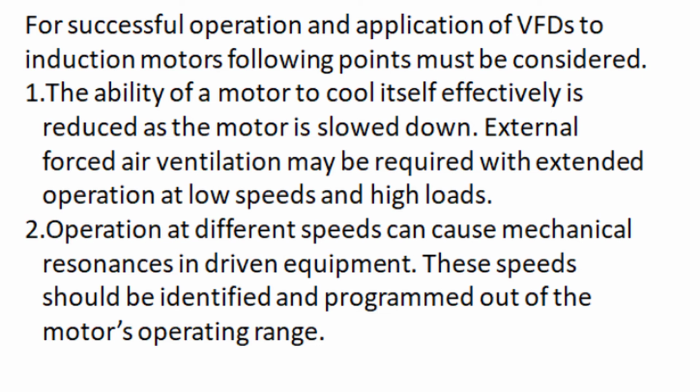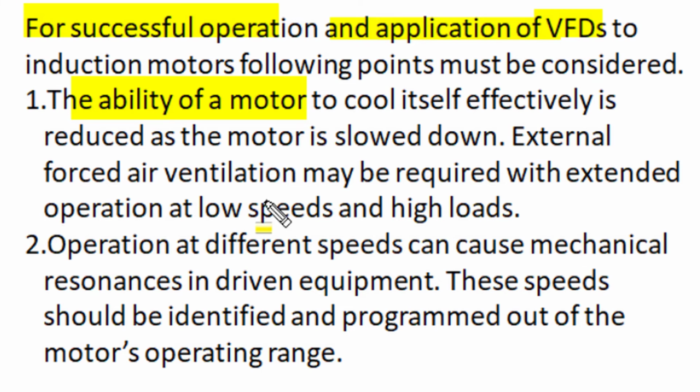For successful operation of a variable frequency drive in the application of variable speed of induction motors, the following technical points must be considered, and they are very important. The key points are: the ability of the motor to cool itself effectively also gets reduced. So in such slow-down conditions of the motor, we have to use external forced air ventilation so as to dissipate heat produced by internal losses, especially at very low speed operation with a high amount of load torque, when the motor is drawing high current and running at low speeds.